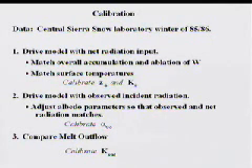So that's essentially the key elements of the model. I've gone through in a fair bit of detail the core parts of it. After we built the model, we wanted to try and calibrate it because there are parameters that we didn't know the appropriate value to put in. We had things like the surface roughness of the snow, which the literature reports. We had the surface conductance, which really just arose out of the way we were parameterizing surface temperature. There were albedo parameters. There was the melt outflow that was related to the saturated conductivity, where the literature gives a large range of it.